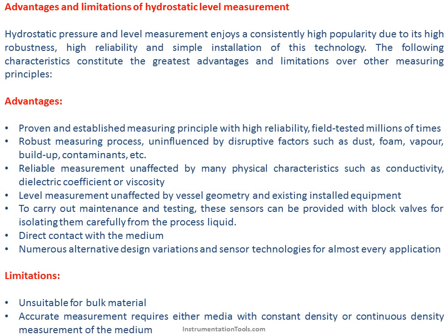Level measurement unaffected by vessel geometry and existing installed equipment. To carry out maintenance and testing, these sensors can be provided with block valves for isolating them carefully from the process liquid. Direct contact with the medium. Numerous alternative design variations and sensor technologies for almost every application. Limitations: unsuitable for bulk material. Accurate measurement requires either media with constant density or continuous density measurement of the medium.